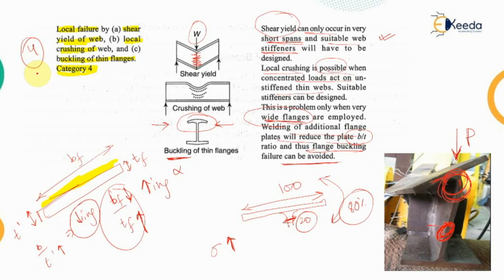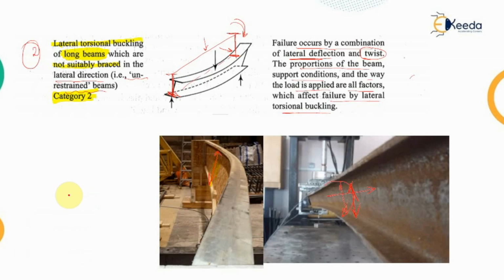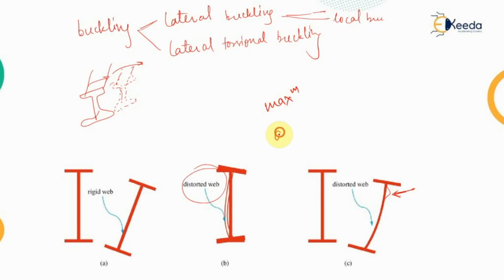Now for the torsional buckling criteria, the code gives different conditions, and for that the code has given different values for the length of member which can be taken so as to avoid torsional buckling, with the help of suitable stiffness factors. Now the deflection formula. In general, the maximum deflection criterion laid out by the codal provision of IS 800 2007 edition is given by delta dash equals K times WL cube upon EI, where K is a constant which depends upon the load distribution and the support condition. W is the load acting on the beam, L is the effective length of the span, and EI are the Young's modulus and the moment of inertia of the steel section respectively, and delta dash is the maximum deflection which will occur under this load on the span.